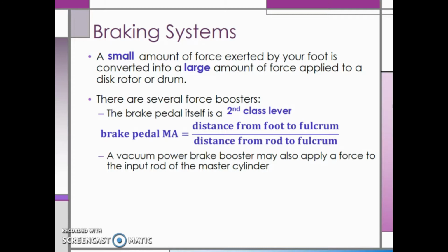A vacuum power brake booster uses engine vacuum to assist in pressing the brake pedal. It hooks up to the intake manifold of a car and requires less force to press the cylinder. Basically, the engine is helping you do the work on the master cylinder when you press it.